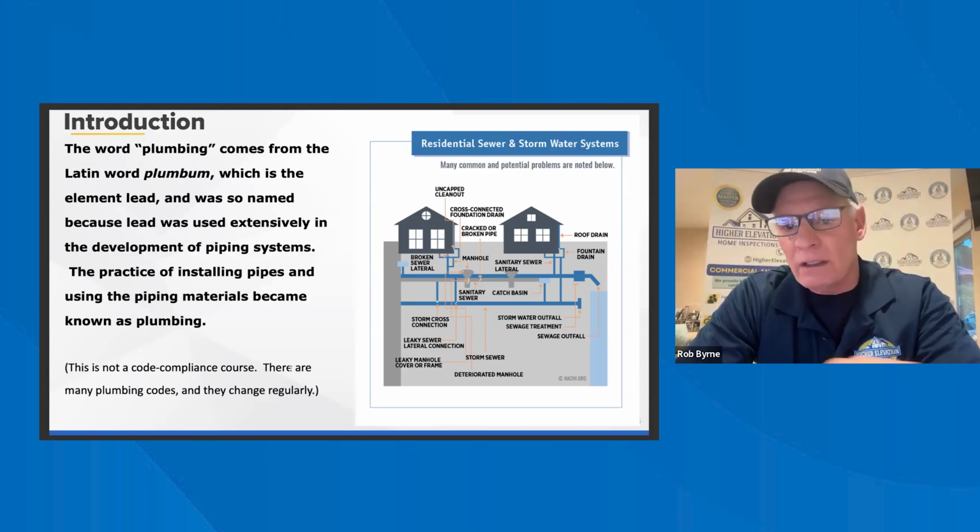But the amount of pressure lost caused by friction is affected by velocity of the water, roughness of the pipe, the developed length of the pipe, and the diameter of the pipe, which we talked about, how if you increase from 1/2 inch to 3/4, it's a big difference. So these are just some of the things that would affect the water pressure.